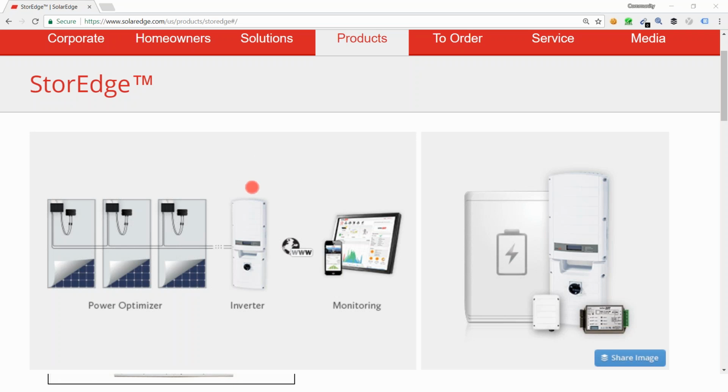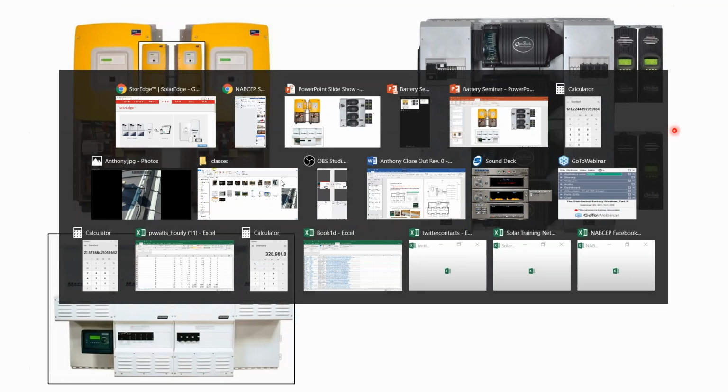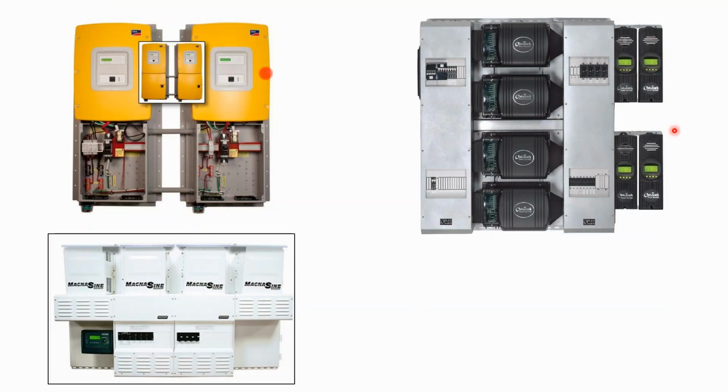Batteries are the same way. You want to send your batteries a constant voltage. Your battery inverters are also voltage regulators in the sense that any power coming into them and then going out to the battery is a regulated, constant, controlled voltage. So your battery inverters are voltage regulators. They go from AC to DC when backflowing through the battery inverter into the battery bank itself.